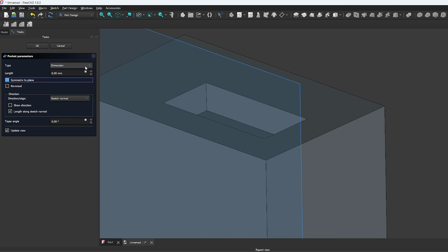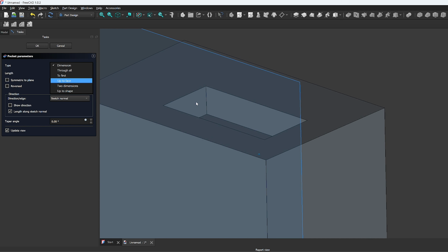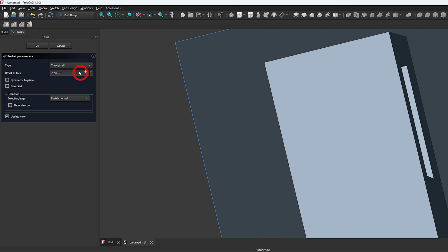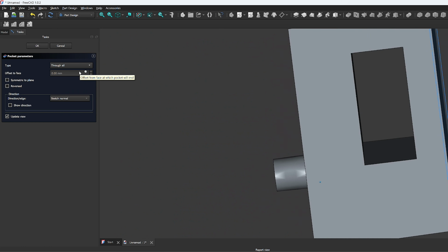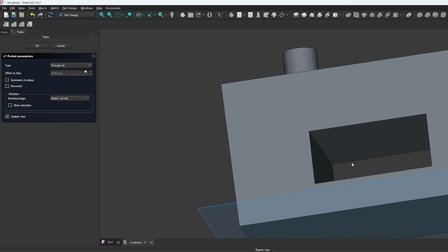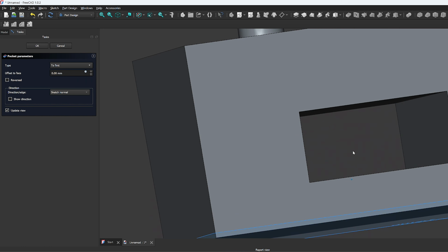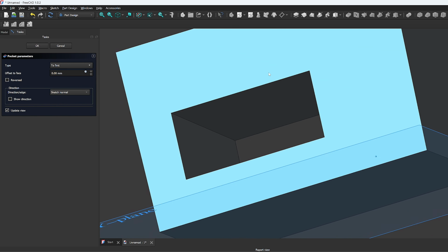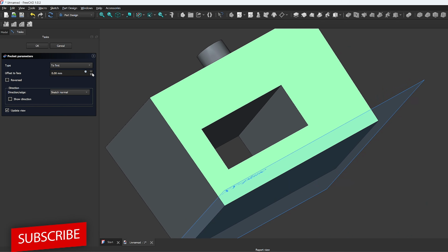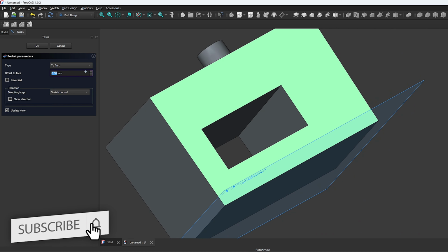And let's also talk about different types of pocket, and here I think I can show you more compared to Pad, because that time we did not have enough reference. For example, if you want this cutout to go through the entire geometry, you can select Through all, and now you can see this is completely hollow and passes through the entire geometry. Now there is another option which is First. First is nothing but the first plane, and whatever first face comes.